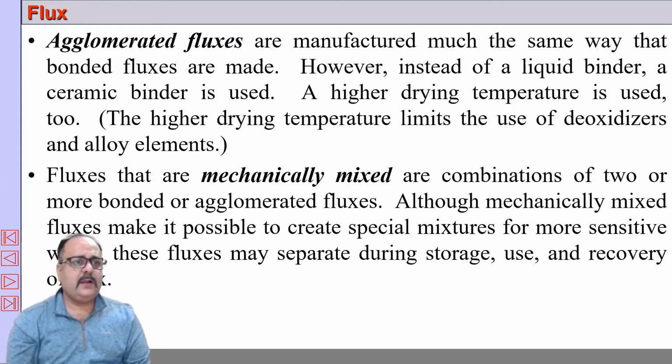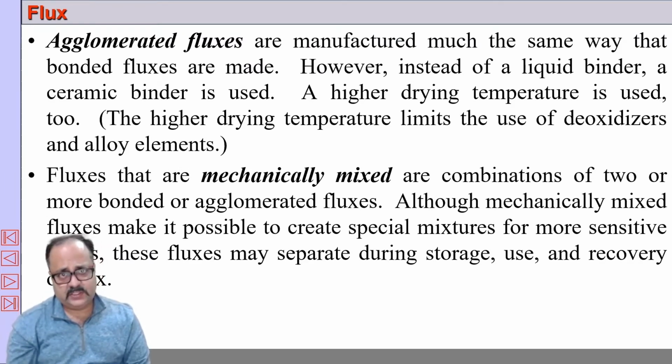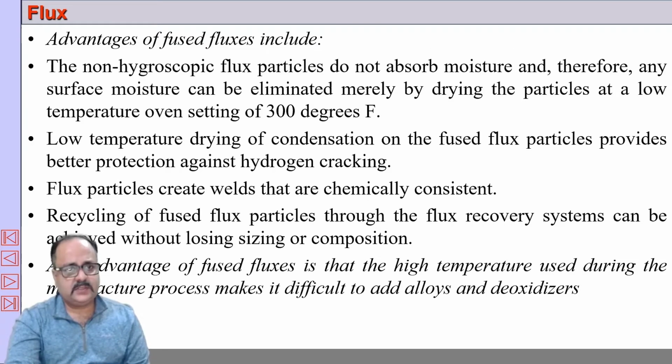And then we have agglomerated flux, which is the same as that of bonded flux. However, we use a liquid binder here, a ceramic binder. And mechanically mixed fluxes are also available, which is basically a mixture of one or more bonded type flux or agglomerated flux to achieve certain specific properties.